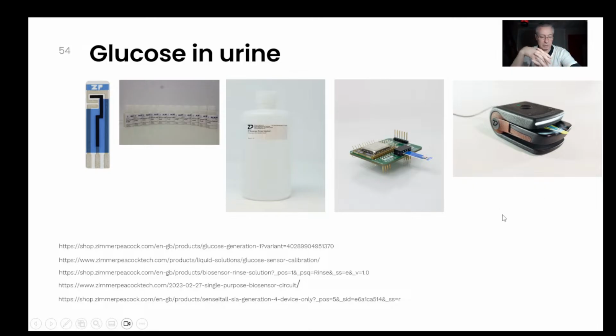So when people ask questions like, oh, I want to do glucose in urine and I want an accuracy of 85%, of course, when ZP answers that question, we're answering it from, I made my first commercial glucose strips in probably 2000, so this is now 2024, so approximately 24 years. 85% accuracy, sure, glucose strips are 85% accurate, but that's after 40 years. To get 85% accuracy today on urine, I don't think anyone's doing it. You probably need calibration routines. You probably need a system approach, not just think that the sensor itself is intrinsically going to do that. And I just listed out at least 2 parameters that are quite out of your control when it comes to urine: pH and electrolyte concentration.